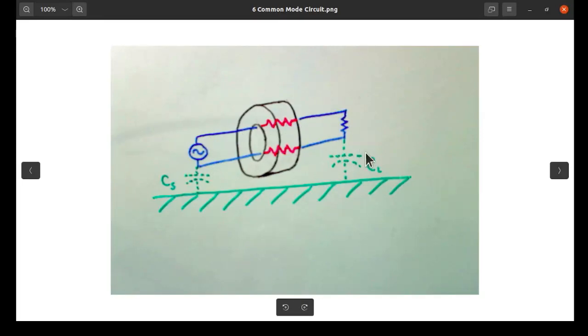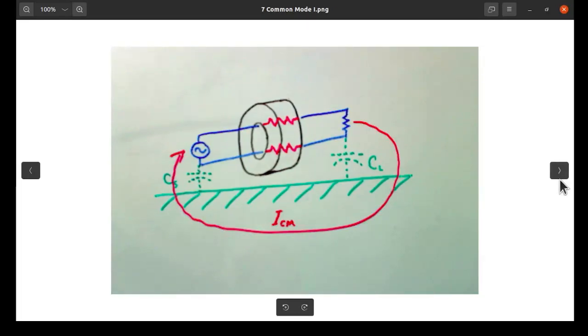I've sort of imaged that before. And that current path is the common mode current. And this is the common mode current that is the point of interest in every discussion of removing it, for one. These resistors impede the flow of this current on both sides of this source. Now, the magic of this is this resistance only appears to this current, the red current, not the blue.